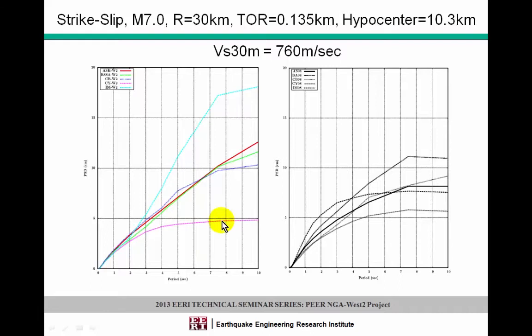And so this is emphasizing that effect in the sense that this high curve up here now is the Idriss model for the NGA West 2, whereas before his model was down here at this level. And again, if you remember, this would be a similar plot for the old model, for different VS30 values within this bin, because he doesn't have it as a function. This is now a function of the VS30 value.